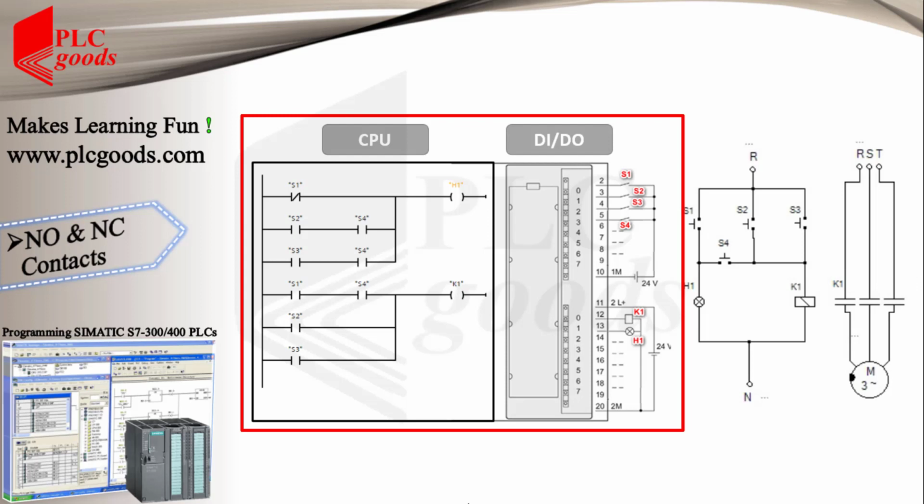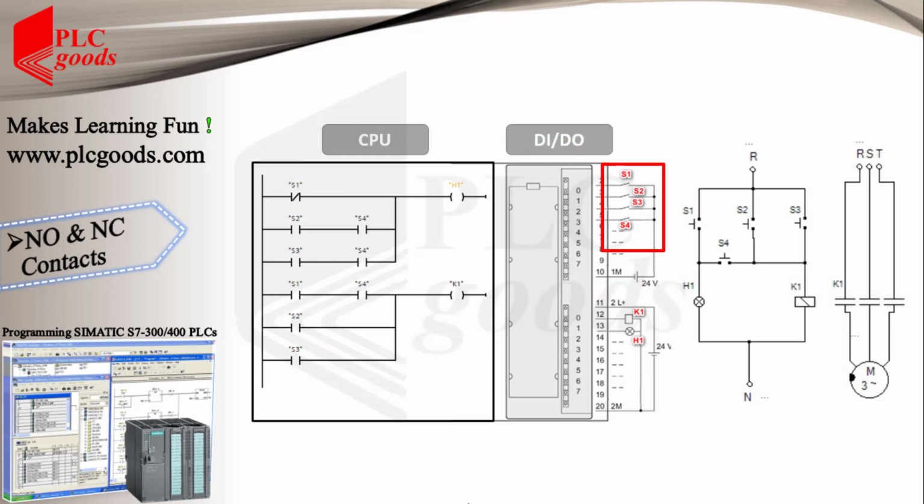Before implementing the next industrial circuit, I should say I'm using normally open push buttons like this diagram. If you use normally closed push buttons at your PLC wiring diagram, you may need to change the type of the related contacts inside the program.